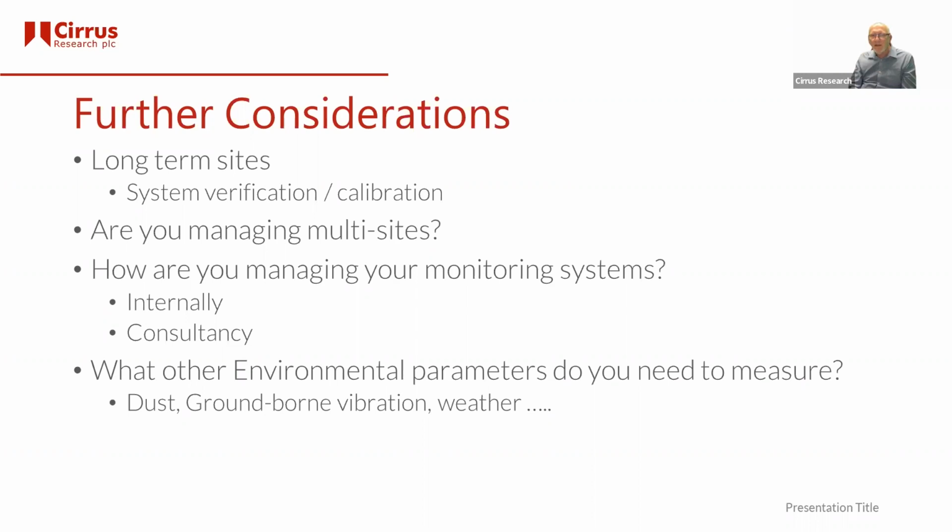Sometimes construction sites are really long term. If they go over a year or more, you just need to think about, if they are long term, making sure that you do have that periodic verification, or what we call calibration, from a calibration house of some kind. Not just sticking a calibrator on forever, but making sure that you get somebody out, or you send it away, just so that it has that calibration in laboratory conditions, to do that full check of the system.